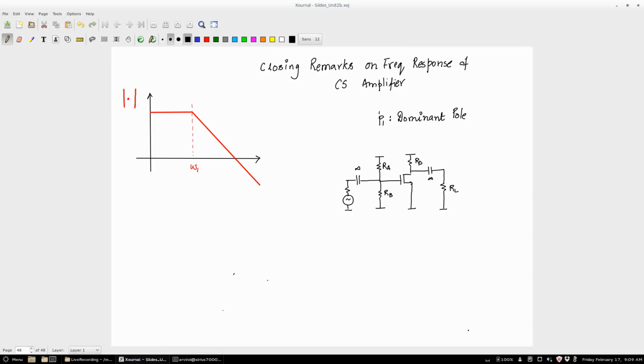So I am talking about that capacitor, correct? Here you should comment on RA, RB, right? And the input comes through a capacitor, right? And I said the capacitors are coupling capacitors. We also discussed as to how we should design these capacitors. Okay, so what do these capacitors effectively do? They prevent the DC from going into the system. So, do you think this response will then get modified? Suppose by chance your signal had a DC component, will it pass through? No. So, what should happen?